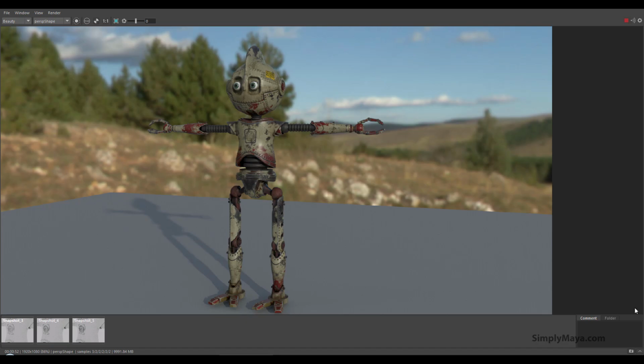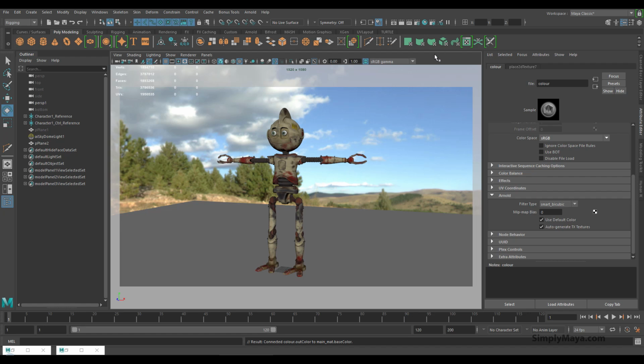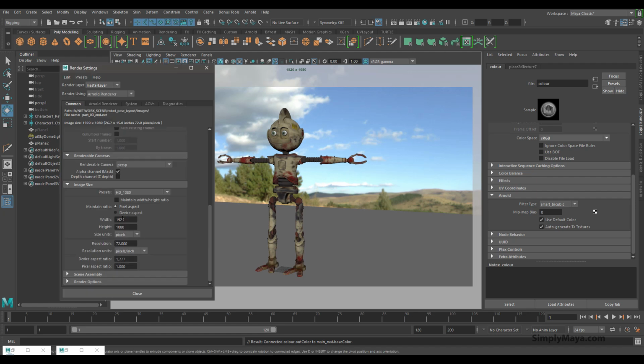So what I'll do with you guys, is snapshot this again so you don't have to, and just show you how much sharper this gets even when it's downscaled on a 1080p monitor like this one, what we get when we render at 4K. So let's stop this and go up to here, and I'm going to set the resolution to, I forgot what standard 4K is, just 3840, that's it.